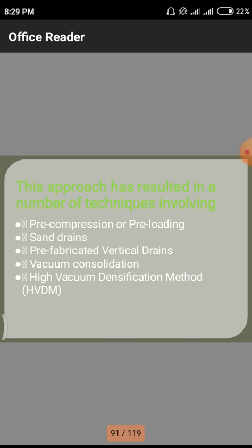So whatever the field we have to dewater, we need to make holes using mechanical equipment. After the holing is over, we need to install drains into the holes, so that all the water lying in a particular soil is absorbed by these drains. Those are called prefabricated vertical drains.